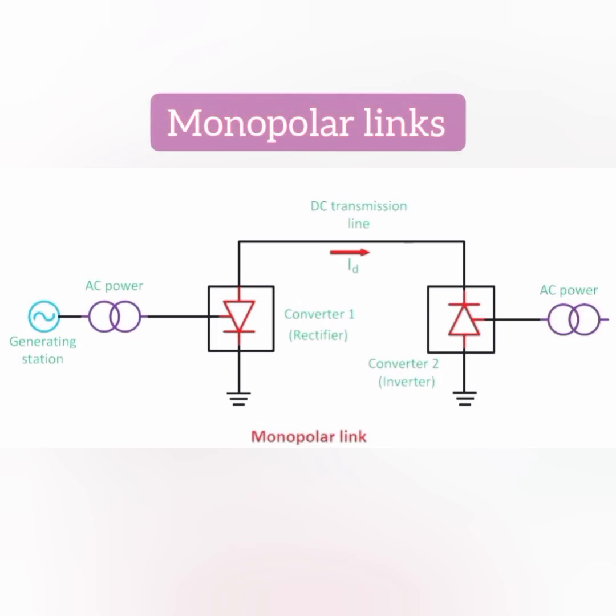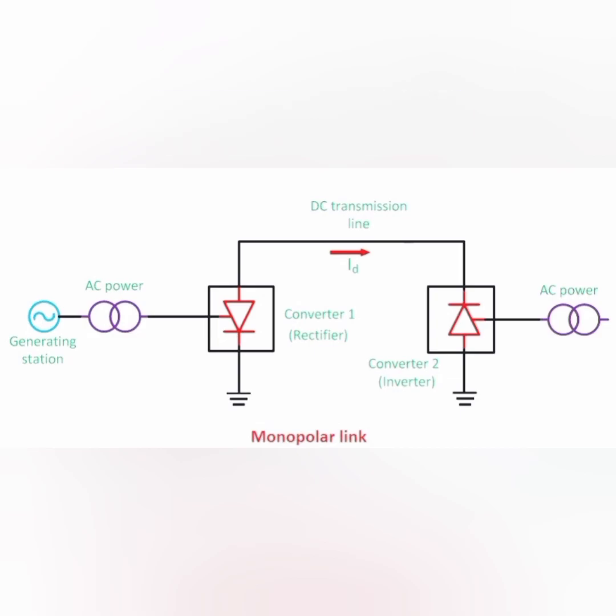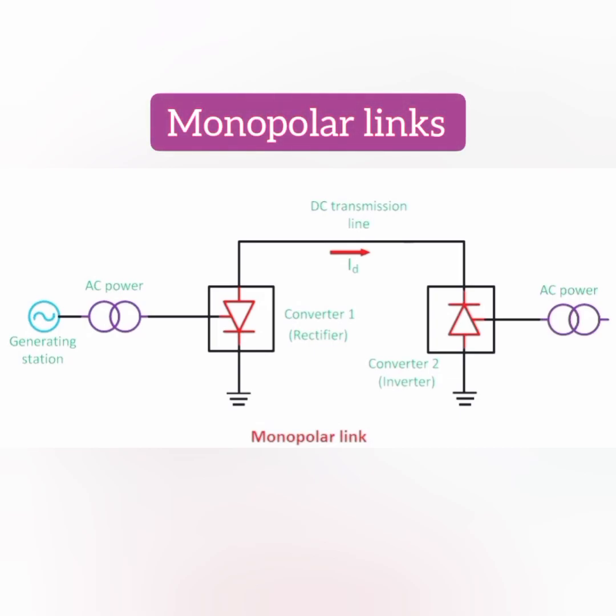And this transmission line can be made as per the required kilometers or required distance, and the individual earthing for both converters is given below. This earthing is made keeping some distance from our converter station, around 15 to 55 kilometers. We make these earthing stations, and for earthing we mostly use electrode kind of materials for earthing the monopole stations.